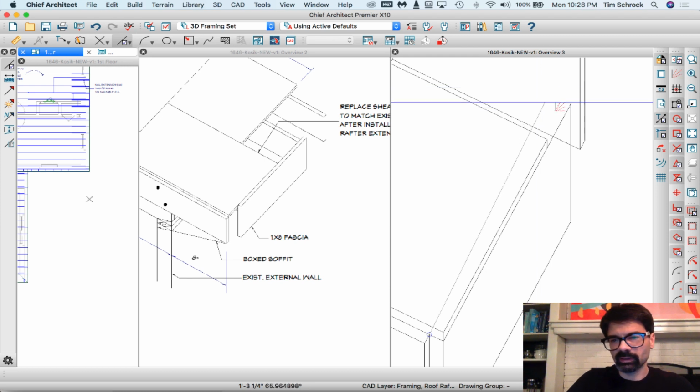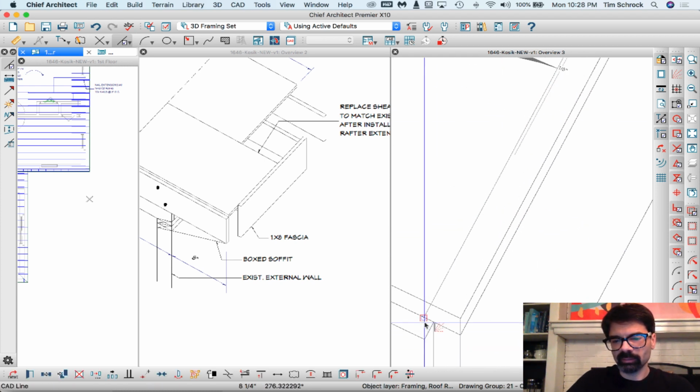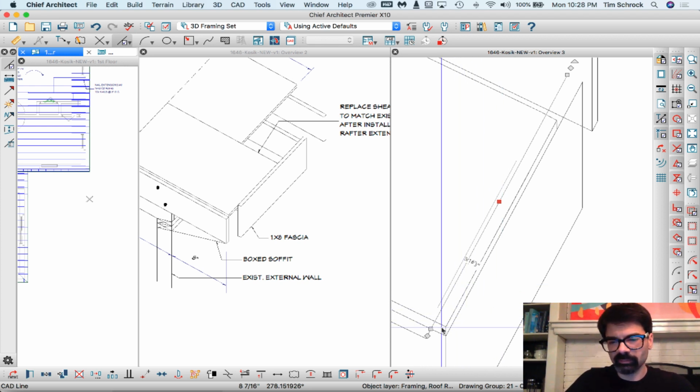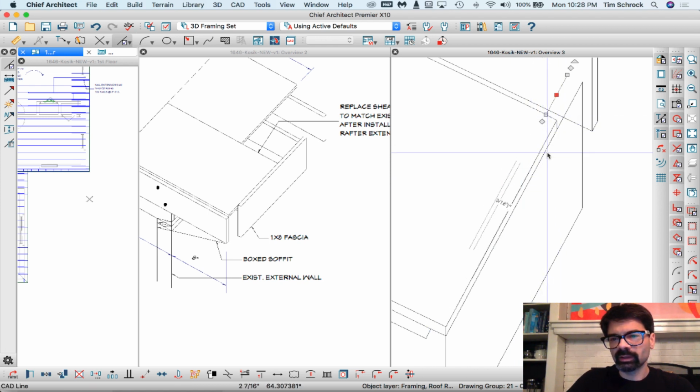Let's turn on F10 and get it close. Command D makes that parallel, point-to-point move from here. Now I'm going to turn F10 off, the angle snaps back on, so this line just keeps going right up and continues on beyond what we can see of the sheathing.